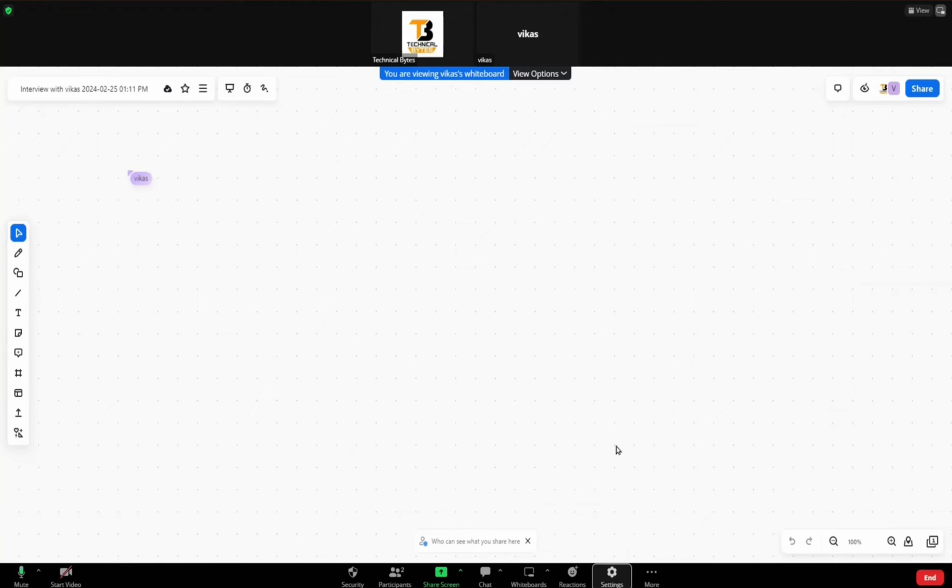Any other answer? Actually, you see, now when you give a clock edge to the first flop, try to understand: the output of the first flop is okay. It is synchronous to the rest of the design, if your design is synchronous. Now, when the positive edge comes on the second flip flop, that means there is a delay of the first flip flop, then a delay of the second flip flop to get the value on the output of the second flip flop. For the third flip flop, it takes three flip flop delays, right? So now if my counter is 10 bits long or 16 bits long, it is width dependent, right?